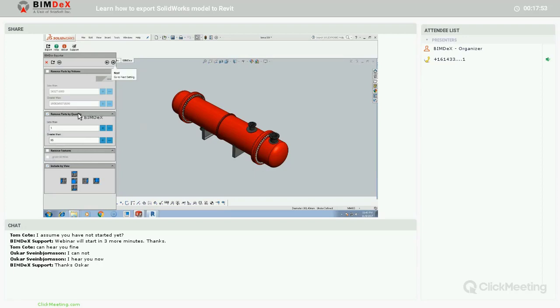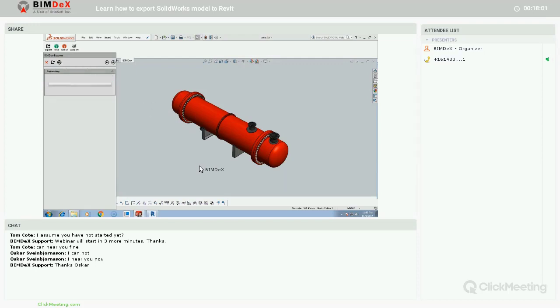Now, this is the basic settings, and you have an option here. After doing all these settings, you could always select this preview, and you could check whether the desired components have been included and the unwanted components have been excluded. Here, as you see, I have just given the numbers of these fasteners, which I mentioned as 95. So the fasteners have been ignored, as you see here.